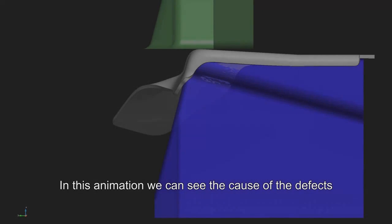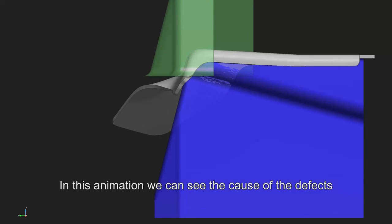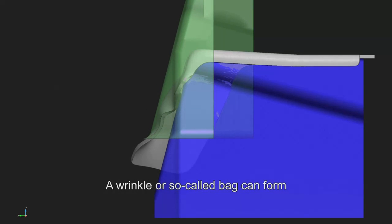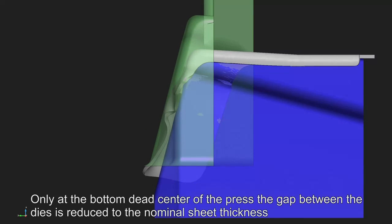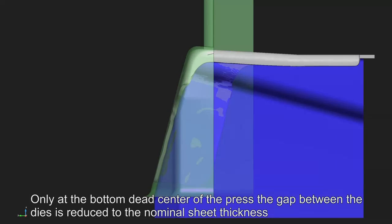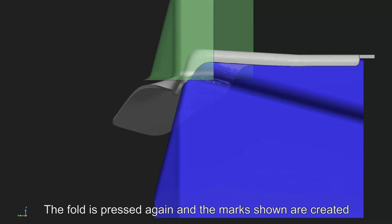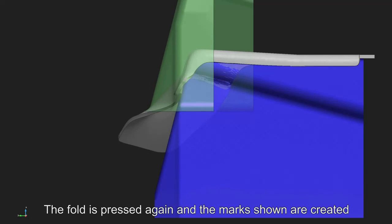In this animation we can see the cause of the defects. Due to the set angle there is space between punch and die. A wrinkle, or so-called bag, can form. Only at the bottom dead center of the press, the gap between the dies is reduced to the nominal sheet thickness. The fold is pressed again, and the marks shown are created.